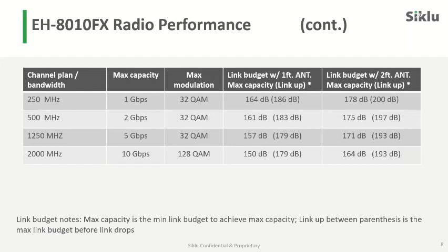I see here another question about transmit power control and capacity. So transmit power control will operate before the capacity is affected when possible. What this means is that the radio is always going to try and maintain the highest available transmit power to have the best signal on the far end and allow operation at the highest modulation and the highest capacity.